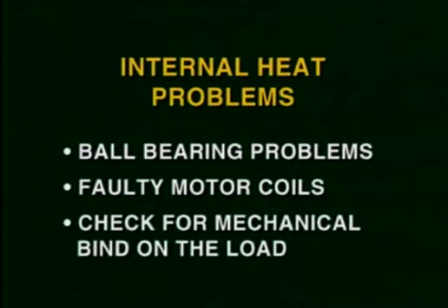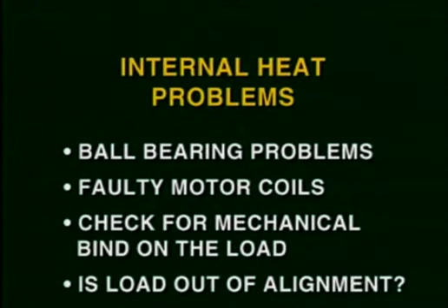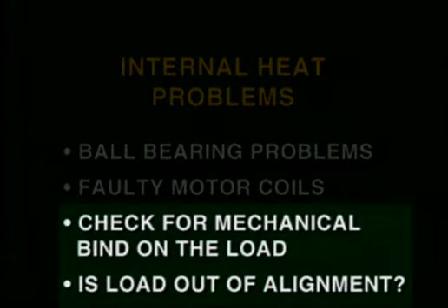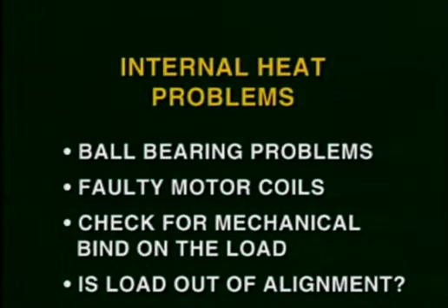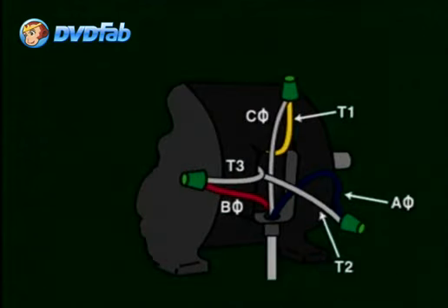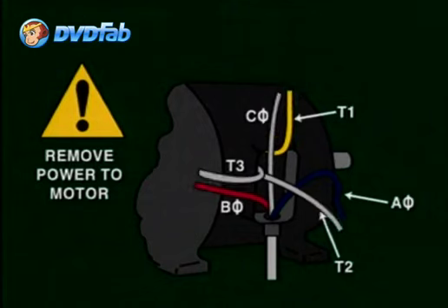Additionally, you should check for a possible mechanical bind on the load, or to see if the load is out of alignment. Both conditions could cause an increase in current that generates heat, which, in combination with a hot ambient temperature, could add to make the internal temperature switch trip. To test for continuity in the windings, you'll need to remove power to the motor and disconnect the wires to the motor from the starter.